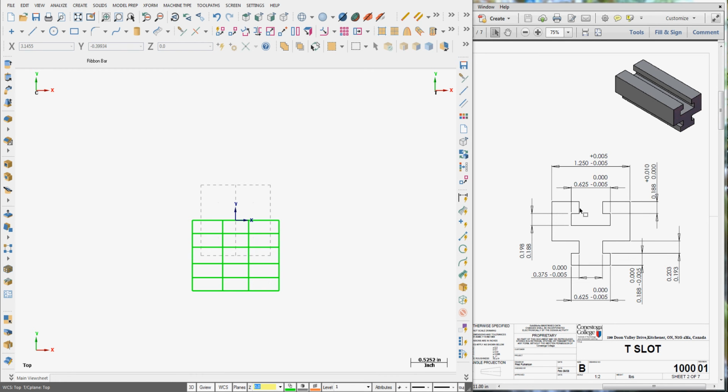So I want to make sure we can visualize this. So this gap is 3/8. Means this section here in the middle needs to go. So let's go back into trim. In divide, I'm going to get rid of this section. So that's this opening. And these will get trimmed later. I need some wider lines. But with the 3/8, I don't need this section here. So we'll get rid of that.